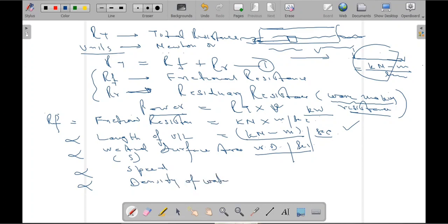Now we always check the density of seawater for various reasons. Let us see for our numericals. For our numericals, I will take this as 1.025. Here there is a decimal, 1.025. I am very well aware that when you are doing the stability calculation, you take the exact one. But here, unless given in the numerical, I would assume it to be 1.025.